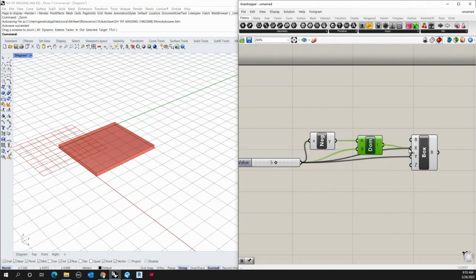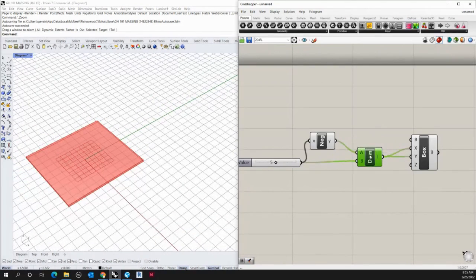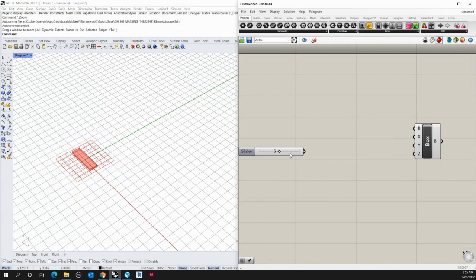And instead of plugging the 5 here, I plug the -5 to 5 domain on both of these. You can see that now my base point is still here, but now it's at the center because I'm going in both directions using the domain. We'll skip that. We'll just use the corners for now for simplicity, but just know that that's how you can control things.